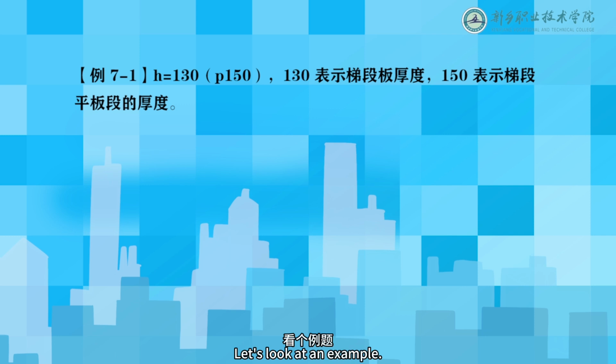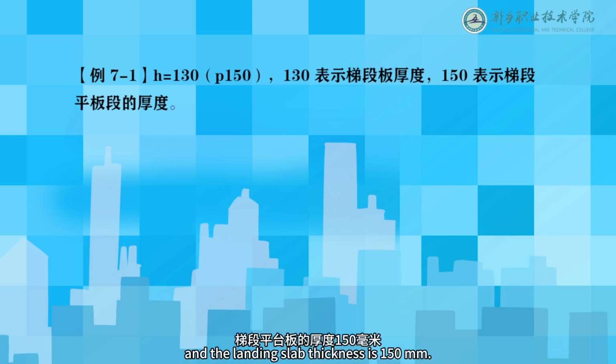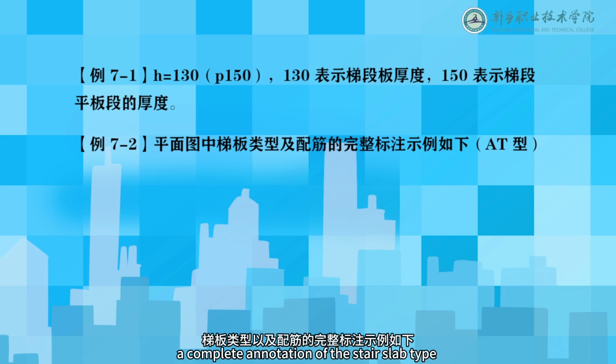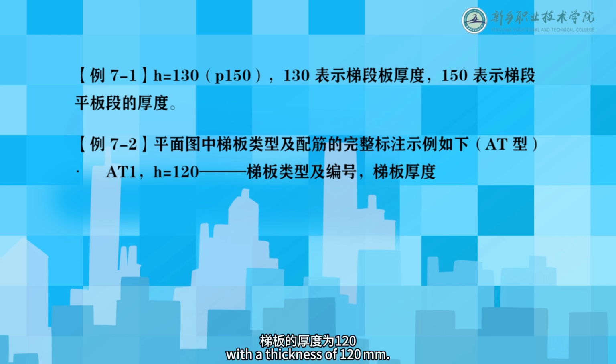Let's look at an example. H equals 130, P 150, indicates that the stair slab thickness is 130 mm, and the landing slab thickness is 150 mm. Another example in the plan view, a complete annotation of the stair slab type and reinforcement is shown as follows. At 1, H equals 120 indicates the stair slab type and code, with a thickness of 120 mm.